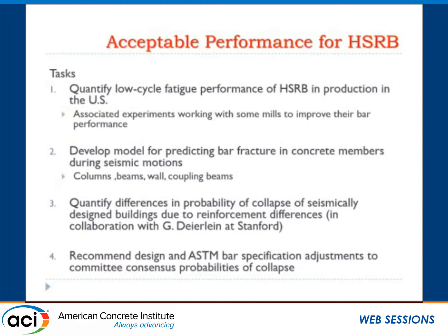We're also, with an associated project, looking at improving that behavior, so we're working with some mills to improve their behavior. From there, we're looking at developing a model for predicting bar fractures. So we have the bar performance, we have the member performance, and we're putting it all together, trying to get the effect on the member performance, and when we can expect fracture of these bars in sections, walls, beams, coupling beams. Then the next task is to quantify the differences in probability of collapse of seismically detailed buildings.